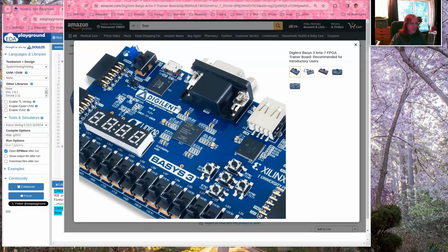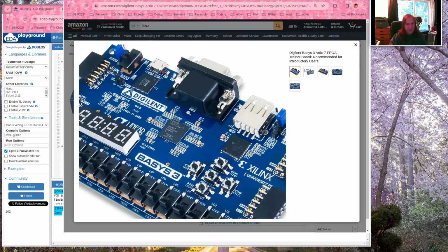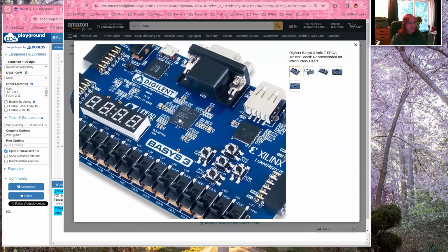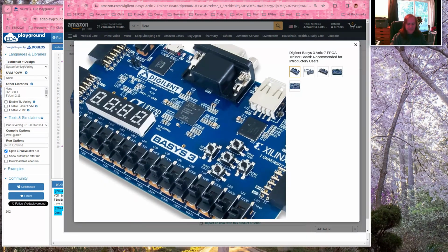And basically you mostly connect to this through a USB port and run software from whoever made this board, and it takes your Verilog code and compiles it and then turns it into programming instructions, and then you can dump those instructions through a cable to this board and actually configure this piece of hardware. And it's non-volatile. Once you do this and you take away power, you throw this in the drawer, pull it out next week, it's still programmed to do whatever function you programmed it to perform. And so this is how a lot of custom chip development is done.